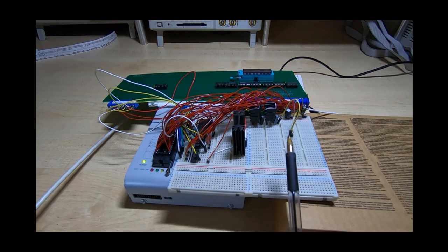I then wrote a file comparison utility to compare the octal file from the emulator that I'd constructed to the octal file from my card. Did a comparison, and there were a lot of differences all through the file, so there were obviously various failures within the ROM set.